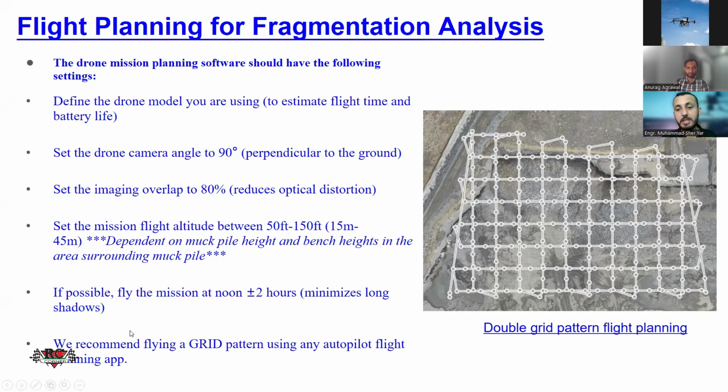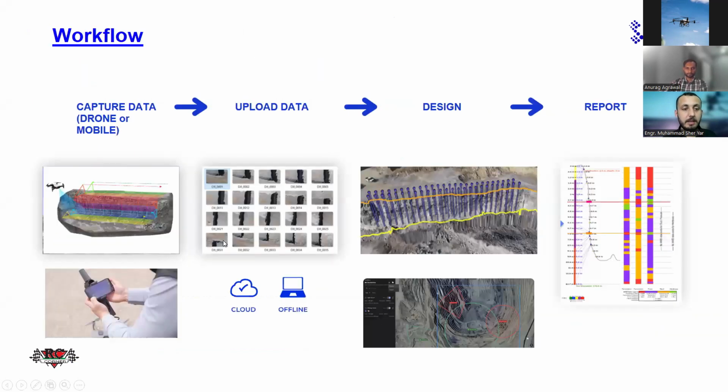About the mission planning on the ground, it should be a grid pattern, crossing each other, so that we can get highly precise data. And there shouldn't be any area left unstitched, like potholes. For that, you just need to take imagery from the drone. You need to fly the drone over the site where you have a mining pit, and just upload the data on the Strayos platform.